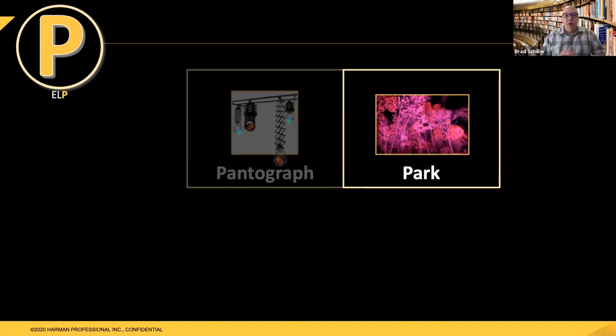So for example, I could take a fixture and point it over on one side of the stage, over on stage right, right where maybe somebody is working on a set piece, and put it in open white. Then I could say park. Now, no matter what else I'm doing, that fixture is locked in at that value in that location. So if I'm adjusting color or playing back cues, that one fixture is going to sit over there in full intensity, open white in that position. So maybe that person on stage can still see.